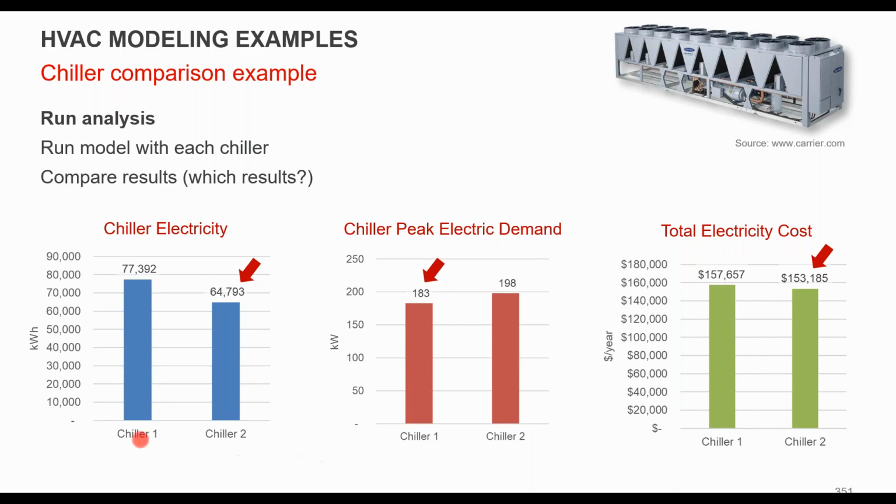So in this case, you might have to look at O&M, the maintenance package and service package that you get from the different manufacturers. The timeline on getting the chillers delivered, for example, might sway it in addition to the actual performance. So in some cases it might not be clear cut, right? $4,000 a year is not a huge swing when your total is 157. So it's a good point.